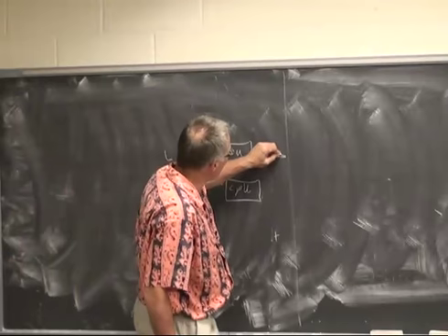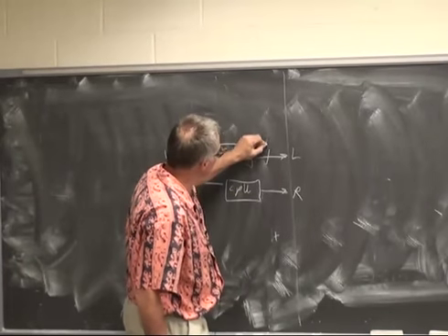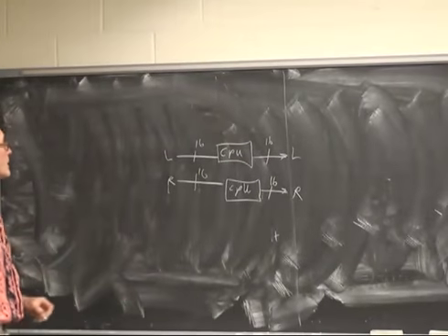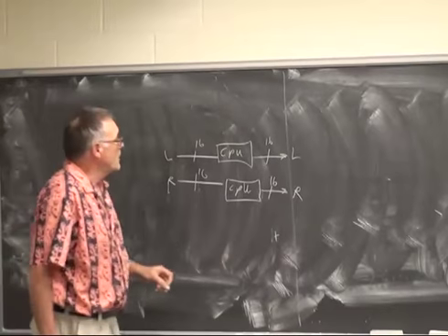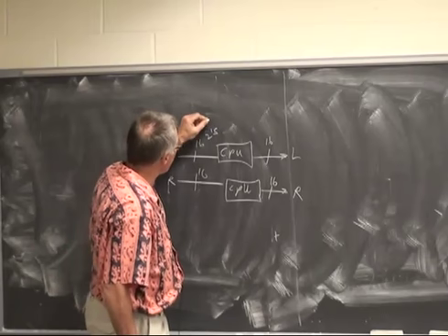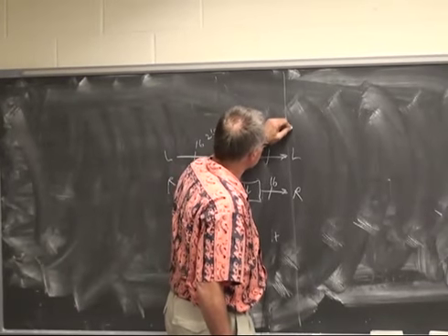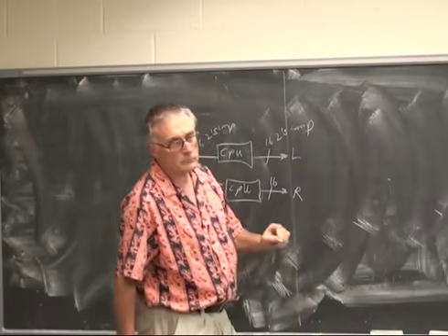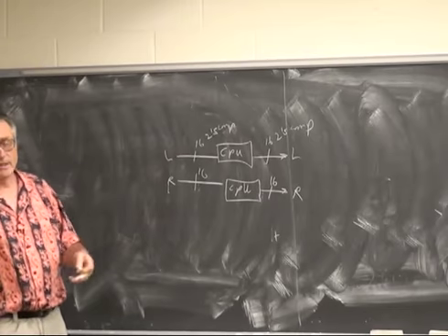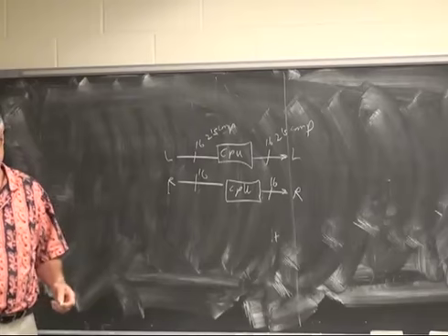And then this is going to go back out to the left and right channel of the codec, and this is also 16-bit 2's comp. So we have to do a 16 to 18 conversion and 18-bit back to 16-bit conversion, but that's easy.